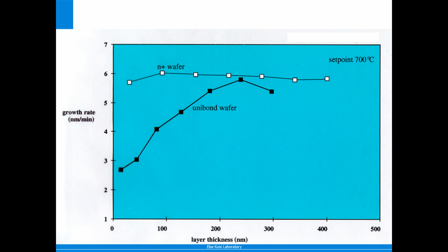To my surprise, in a production situation, people don't bother. Some don't even know that this effect exists, because they are running the same mask day after day. And when they get something else after a couple of months, they tune it in again, and they don't even realize that this is going on. Because the temperature increases while you're growing, and you're changing your main content and the dopant incorporation, but apparently it bothers nobody. So let's keep it this way, but it's not a nice effect.